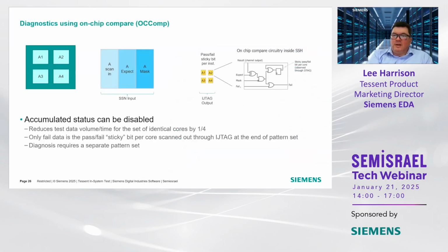I mentioned diagnostics. So there's several levels of diagnostics you can do with the in-system test controller. It is possible to do full detailed diagnostics as you would do on an ATE, but also typically used is the less granular diagnostics, which is essentially looking at the various cores within the design.